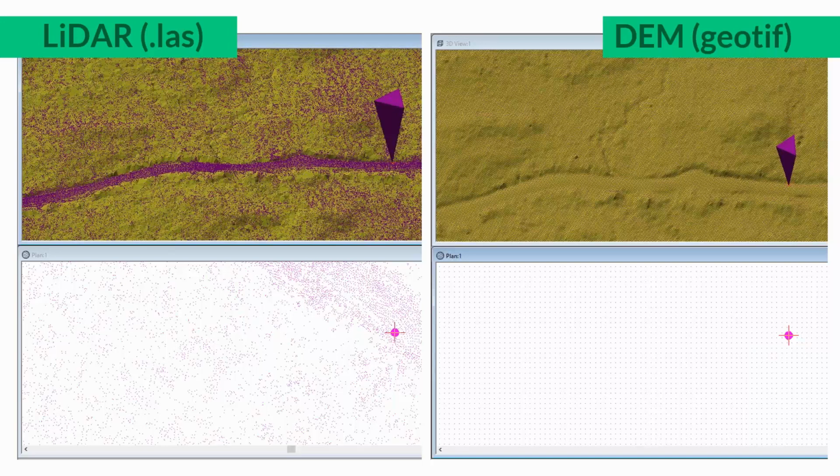So the difference is the LAS files are the actual points that the scanner collects when they're scanning an area. And the DEM data is a derivative of that. So in order to get to a DEM, when it's being processed, they'll take the LAS files, create a TIN, and then they'll grid them. And we see the points that are set on that regular grid are showing up.